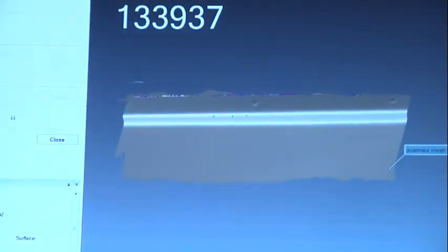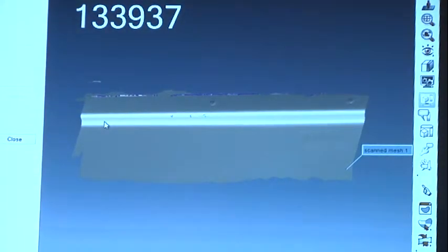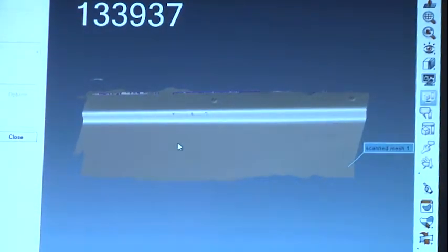And at the end, because we did delete the area where there was noise and rescan it with proper settings, we now have a nice scan. Now, this metric is this one here, high noise level, and you can control the maximum standard deviation.